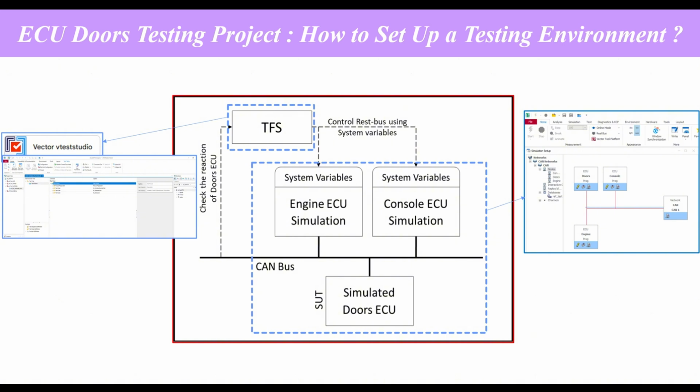We also have the TFS, test framework system. It is implemented using vTestStudio, and it manages the automated execution of all the test cases. It sends stimuli to the doors ECU via the CAN bus, of course. It also monitors the ECU response and compares it with the expected result defined in our test plan.